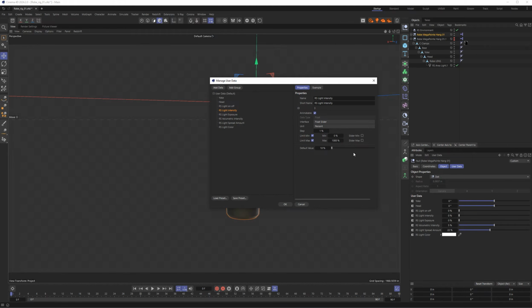So I decided in this case to actually just bump it up to 1,000. And that seems to work pretty well and get it bright enough. I think I did the same thing for the exposure. Yes, I did the same thing for the exposure. And so your whole scene will burn out if you max both of these out. So I just wanted us to have the most options there, but it's probably overkill.